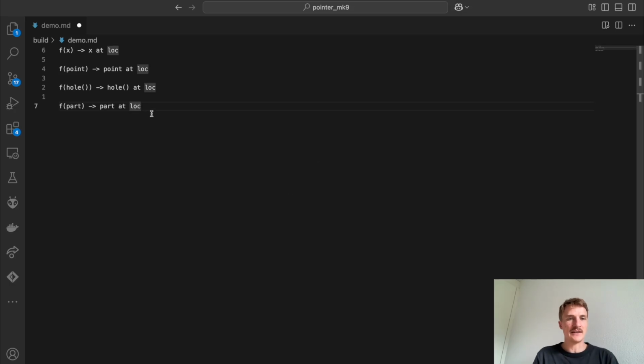And so hopefully you can see here that this doesn't require any dependency on the previous step. Because if you want to define a sketch, it only depends on the function f. If you want to define a geometry, you can also just call a given function. And if you want to define an assembly, same thing, you can just call this function. So now if we want to change your sketches, your geometry, and your assembly, you can just modify the function f, and it's going to impact all of those without having dependencies between them. So technically, this should make for a more stable way to build CAD and also to automate the way we generate assemblies.